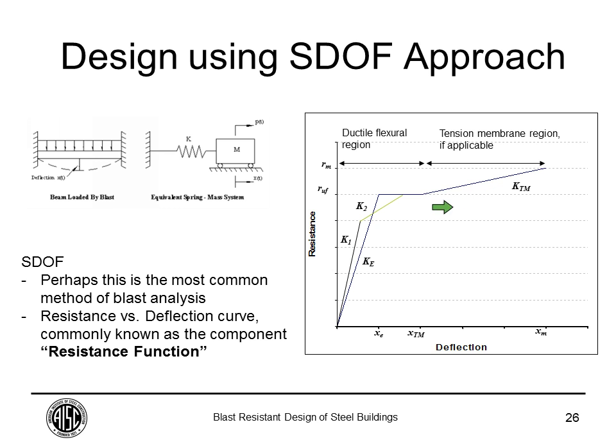So you can see that if you account for tension membrane behavior, you have a lot more area under that curve, as opposed to if you were just doing a simple bilinear type of resistance function, because your connections do not allow for a tension membrane, then you will just come here and then come down, so you lose a lot of energy.